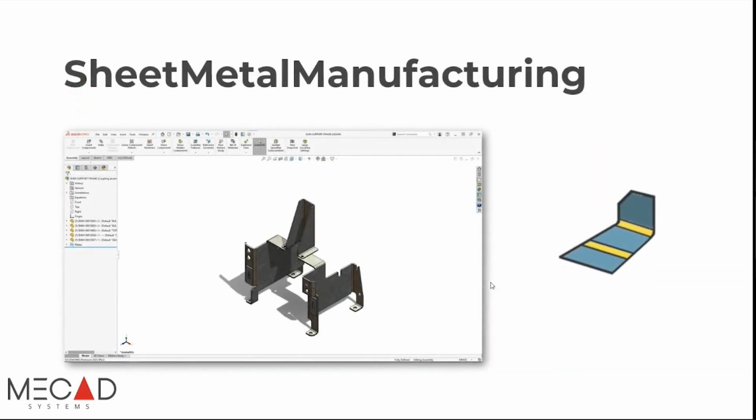The first one that I'm going to look at is sheet metal manufacturing. What this tool allows you to do is open up essentially any part or assembly, whether they have, let's say, a mixture of sheet metal items and weldments items, or even one sheet metal item and the rest of them being, let's say, a dumb solid. This tool will extract those sheet metal items out of your assembly, and it'll convert that assembly's parts into drawings and export those drawings as a DXF with the flat pattern that you included.